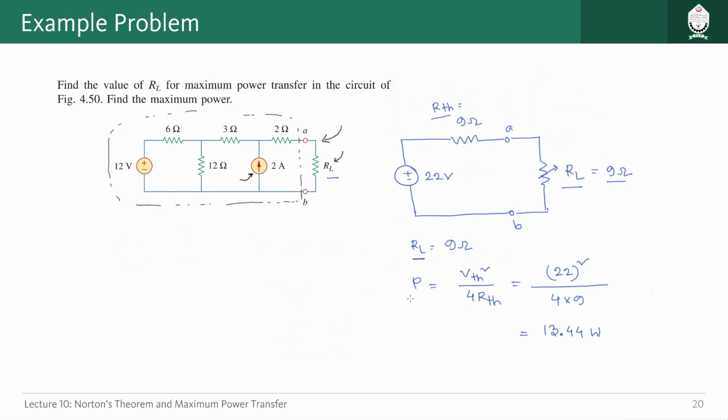So in this way you can actually find the value of RL for maximum power transfer, and then you can also find the value of power delivered, the maximum power to that load.